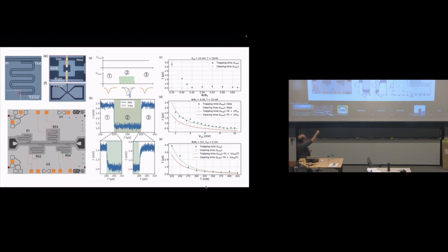So previously I just had 1 path, but now I make it 2 paths. And by putting a pi phase shift over here, you make this element a quantum sensor practically, right? And we can show that this sort of a SQUID can detect if 1 Cooper pair is broken, it gives you enough frequency shift that you can actually pick it up in the sensitive device. So this is the chip that we have.